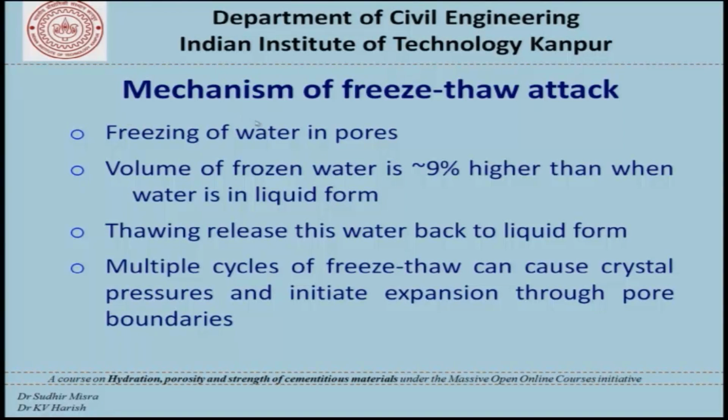In that case, what usually happens is, concrete contains pores and it also has water in it, and when the temperature goes to the freezing stage, the water in the pores is frozen. When it is frozen, the volume is approximately 9% higher compared to the volume of water in the liquid form.